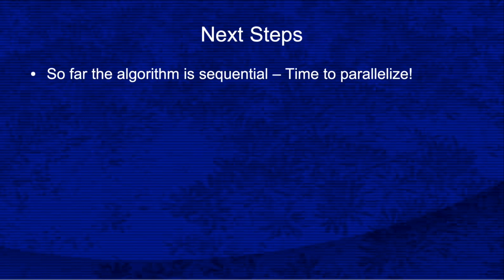It's time to parallelize the algorithm. Once again, I'm going to apply 3-2 compression, that is, a Wallace tree, to avoid as much as possible the cost of propagating the carry bit. Let's review how I previously used 3-2 compression.